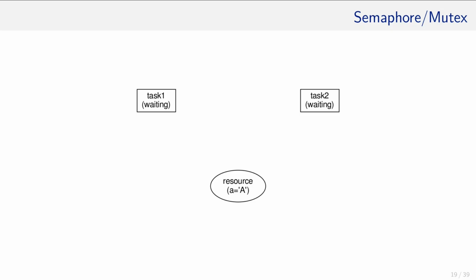If the resource has only one token to give away, as it is the case in this scenario, the token is called a mutex. If the resource has multiple tokens and could allow, for instance, both tasks to write to the buffer because it has the space for two write accesses, these tokens are called a semaphore.